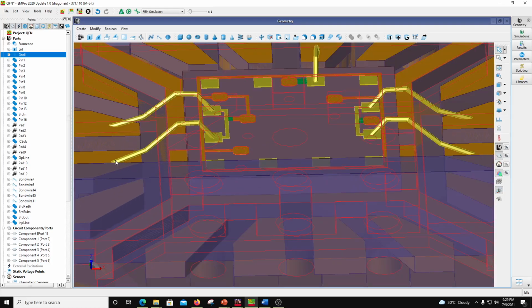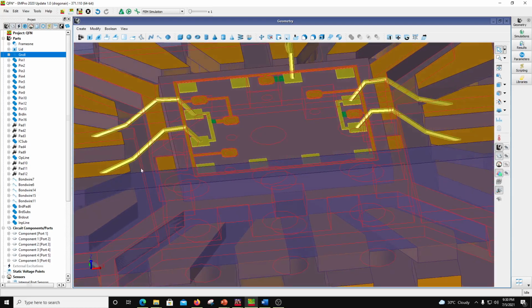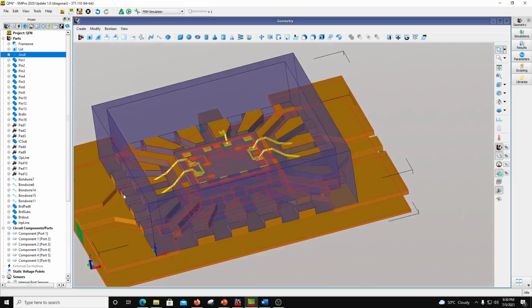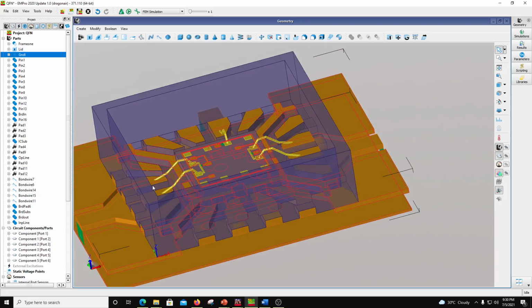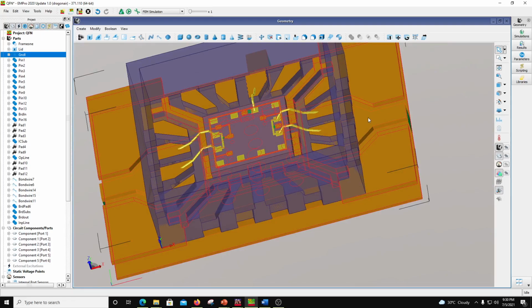So there is C on the pad, which is a board pad. So what you see here, this QFN is sitting on a board, right? And then you have got this line which comes in for the input and the line which goes out as the output, right? And then there is a bias pad for the biasing also.